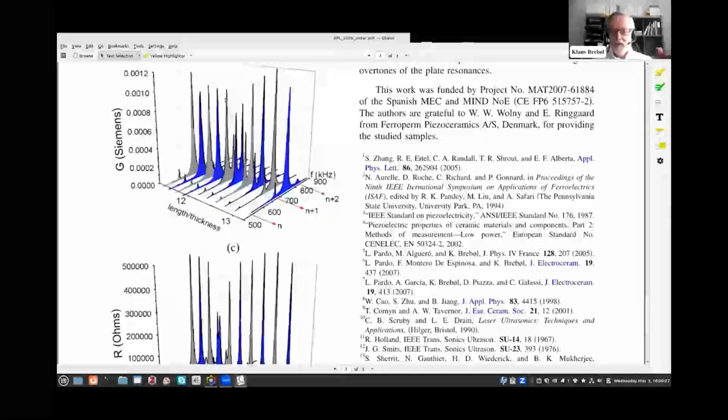So by using an extreme or a larger, at least, length over thickness ratio, you are probably ending up in the solution that is given by the more traditional methods. But this you do at the cost of increased losses, because you are at the same time increasing the frequency, because you normally do this by thinning down the plate.